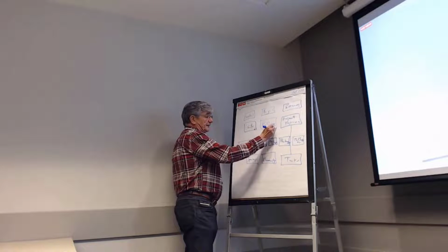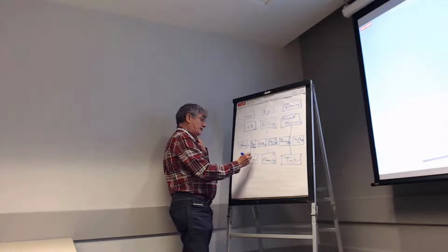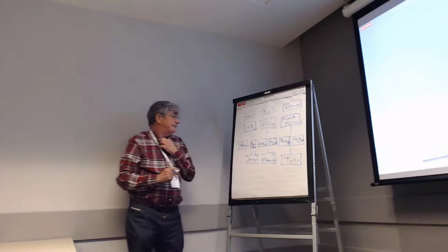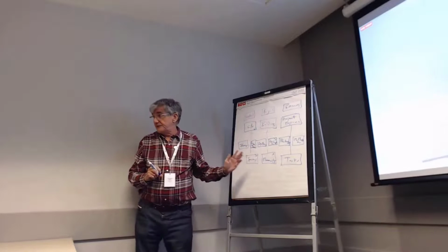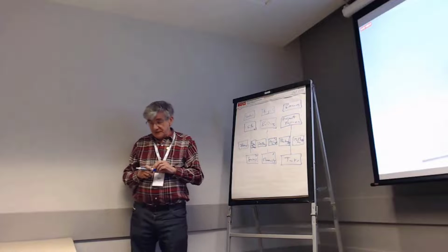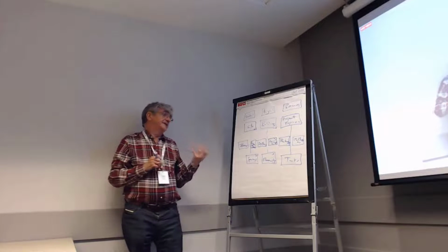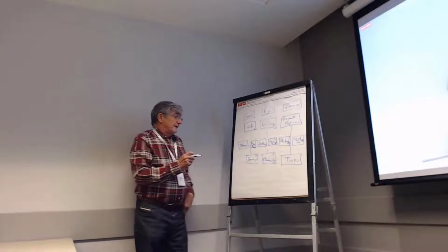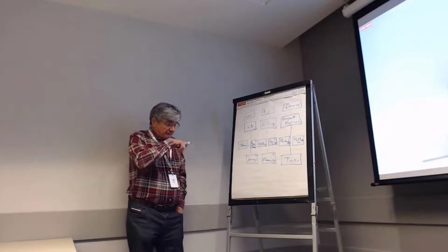The site, the building, the products, the elements, probably the spaces will have geometry too. When we're talking about attributes, any of these things can have attributes, and any of these things can have documentation attached to them. The other thing that doesn't get mentioned very often is that the IFC tracks relationships.